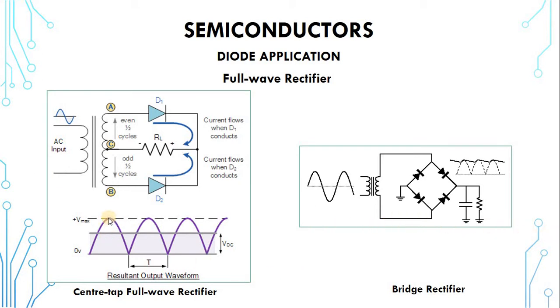It means that by the time it is getting here, that's when the current from the rectifier comes and charges it again, and charges it again, and so at the end of the day, you are not even going to have it drop a little. It will almost be like a straight line. By so doing, we have fully rectified the AC waveform into a DC. So a bigger capacitor will give out a smoother waveform, and this is what we want.